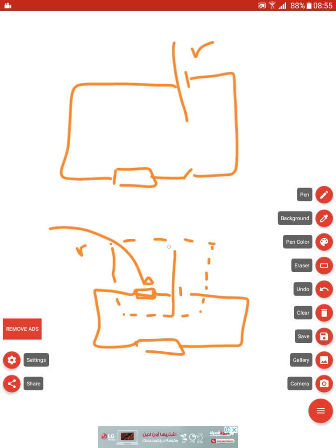If the switch is open, we have no current. So if you put a voltmeter in parallel here and the switch is open, the reading of the voltmeter equals the EMF of the battery itself, let's say 3 volts.